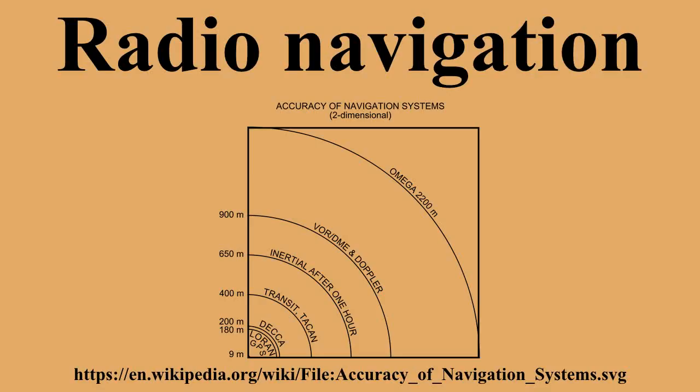The U.S. military also introduced a VOR-like system known as TACAN. It differed from VOR primarily in its modulation system, adding a Lorenz-like signal to accurately define the center of the rotating beam and thereby improve accuracy. It requires 5 receiver channels and additional electronics, an expensive requirement when it was introduced.